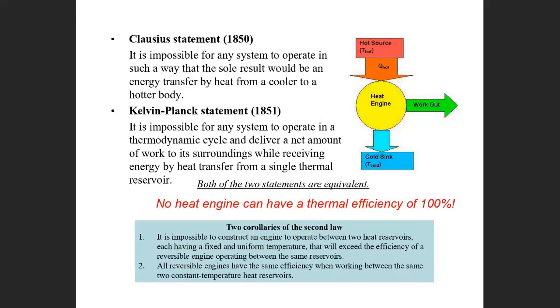Similarly, there are other statements whose observations are the same as Carnot's. The Clausius statement is that it is impossible for any system to operate in such a way that the sole result is an energy transfer by heat from a cooler to a hotter body.